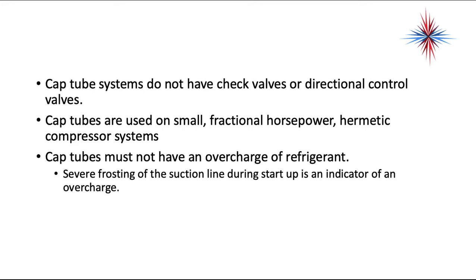Cap tubes must not have an overcharge of refrigerant. Severe frosting of the suction line during startup is an indicator of an overcharge. Cap tube systems and fixed orifice systems are what we call critically charged systems. They have to be charged to exactly what the manufacturer specification is. Now, if you do add a filter dryer to a cap tube system, and if that filter dryer is larger, you will have to adjust the refrigerant charge. And I believe on some of the certification tests out there, that is a test question.